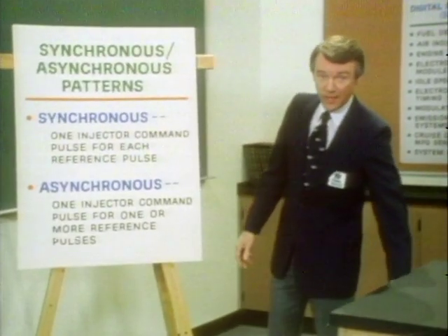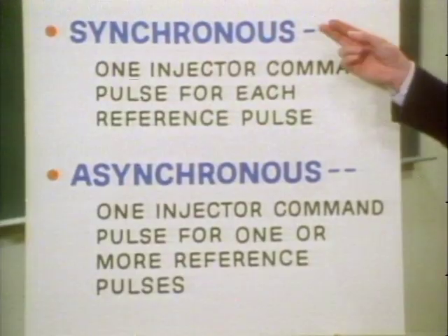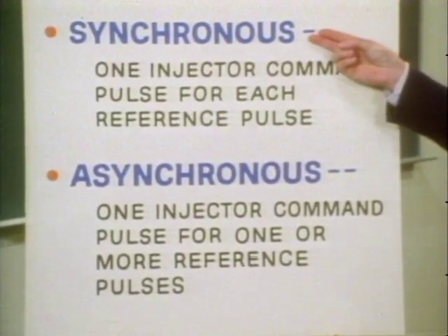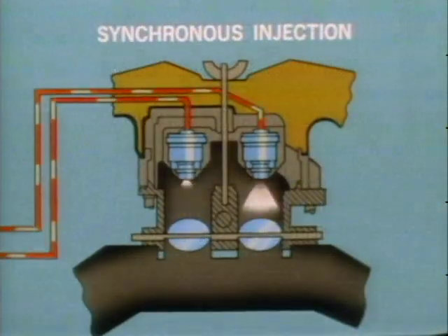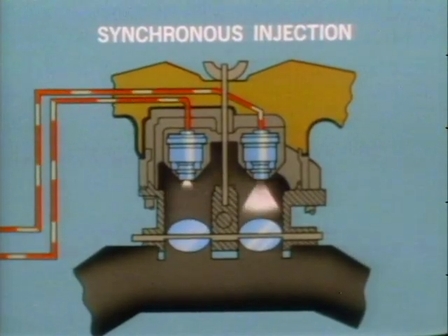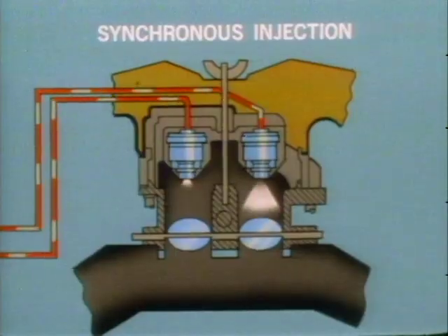synchronous and asynchronous. Synchronous commands are issued under most conditions, with one injector command pulse issued for each distributor reference pulse, and the injectors being alternately activated.